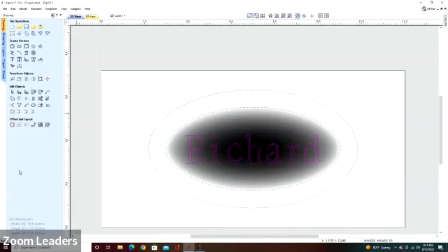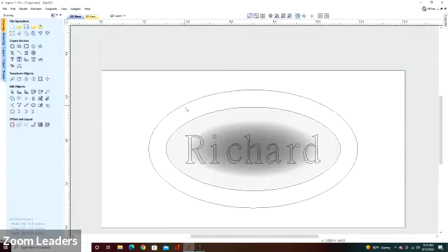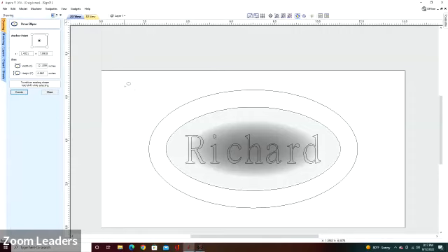Then the next thing you want to do is start actually doing your design. And there are very simple elements that we have on this. We have a couple of ellipses and we have some text, very simple. To do an ellipse, that tool right there draws from the center. You can shape it, play with it, do whatever you want. You can also go in and enter the parameters here. For example, I could say, I want that to be at 0, 0 and apply it. And the ellipse is centered at our 0, 0 position.